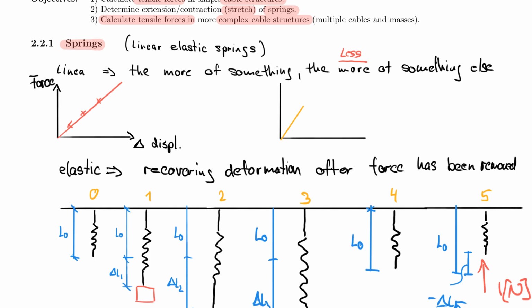Steel is initially elastic, you can pull on it and it goes back to its original length and so on. But once you go beyond a certain delta L, like once you put a lot of force on it so that it stretches too much, so you can also say that you have a delta force on there. So once you have too much force on there, you go beyond this point, then the material actually starts to become plastic and it really looks like this.